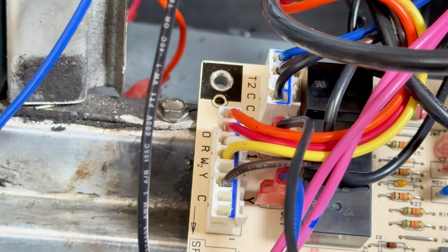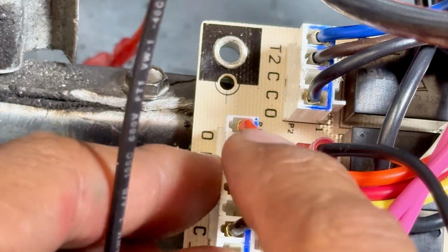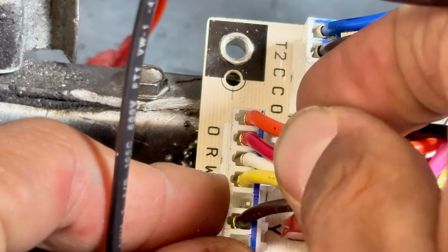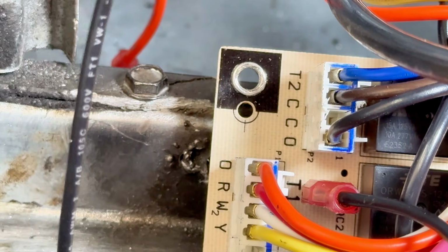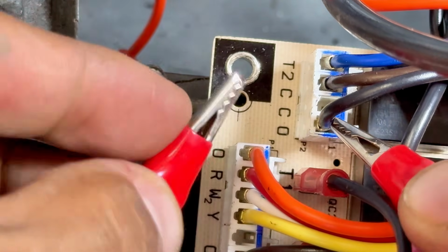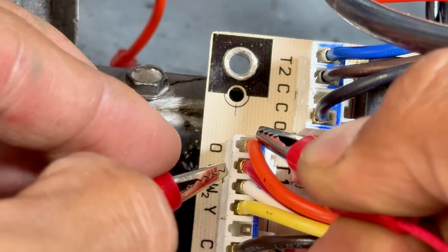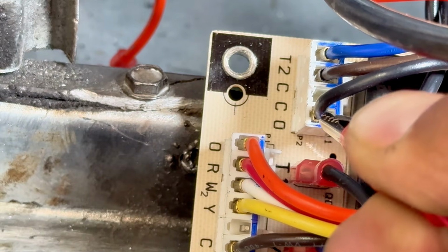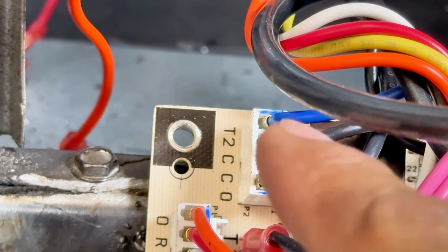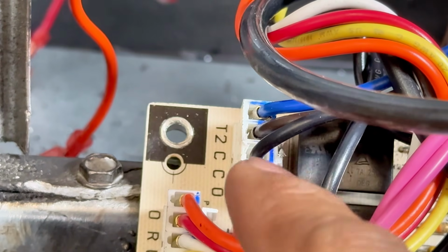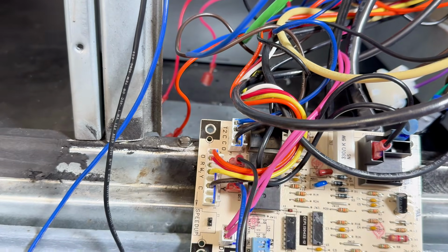Let me make sure you guys are able to see that. Right there. Orange wire, O. Once that O, this orange one, gets 24 volts, internally, you don't see it, but it kind of does like a little alligator clip action. 24 volts goes here, and then it comes out from this black one. Guess where that black wire is going to? Well, if you said reversing valve, you're correct.